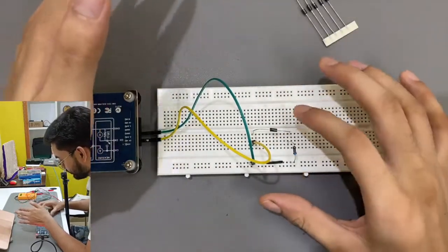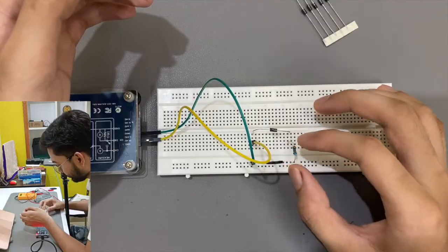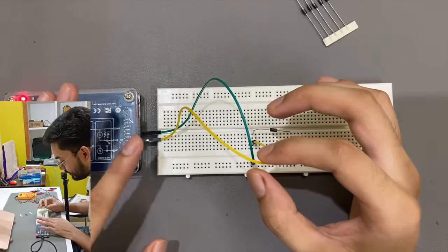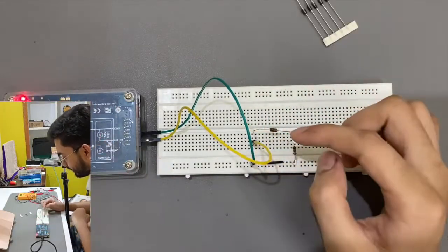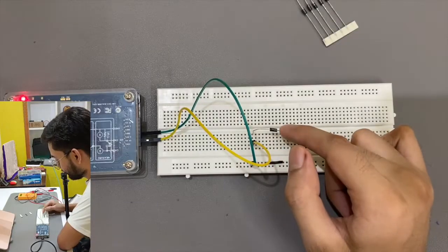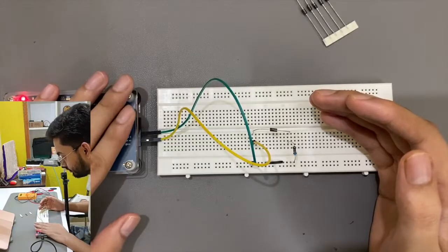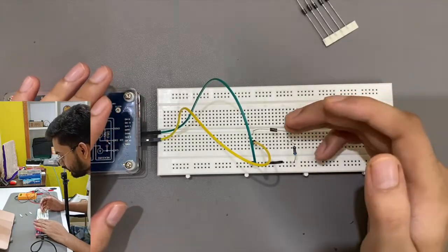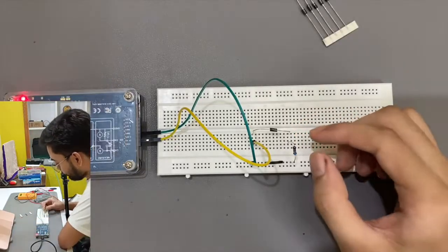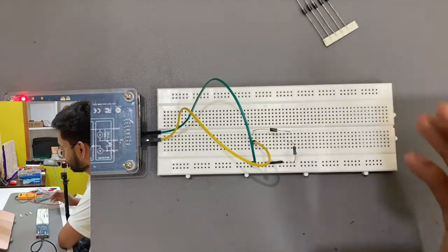This is my circuit, in which I use the same diode which I showed you. This is my resistor of 1 kilo ohm, and these are the pins of the external voltage source which I am providing through the ADALM1000. This yellow wire is connected to channel A, which is positive, and green is connected to ground, which is negative. We clearly see that the positive wire is connected to the positive of the diode and the negative wire is connected to the negative of the diode, which means this condition is forward bias. But to flow current through the diode, the value of the external voltage source must be greater than the barrier voltage. We will find the barrier voltage of this diode by applying various values of external voltage from the Pixel Pulse 2 software, and we will measure the current of the diode across the resistor through a multimeter. So let's get into it.